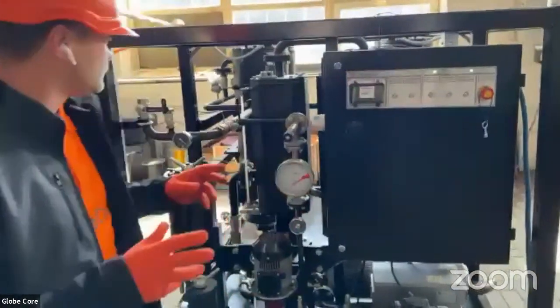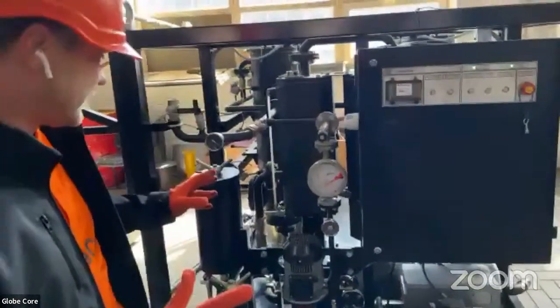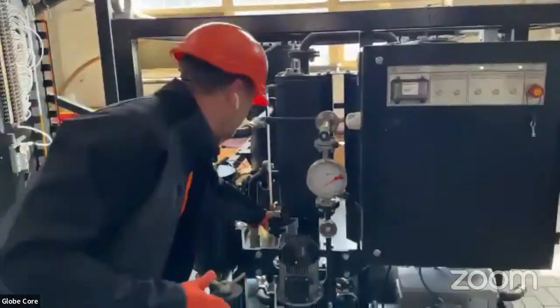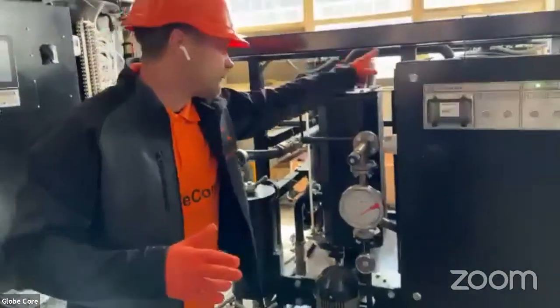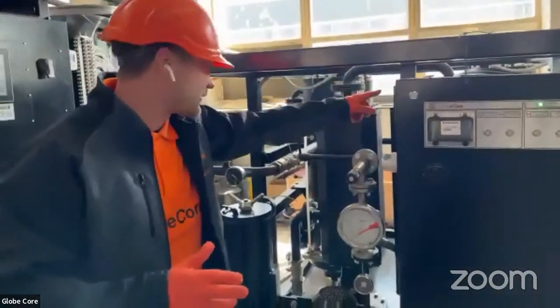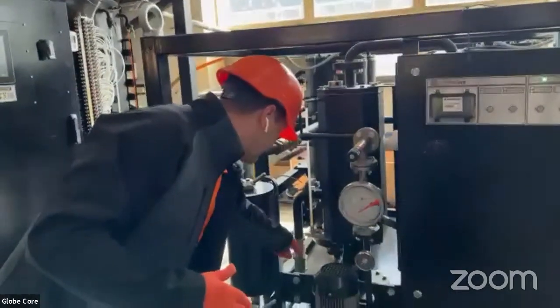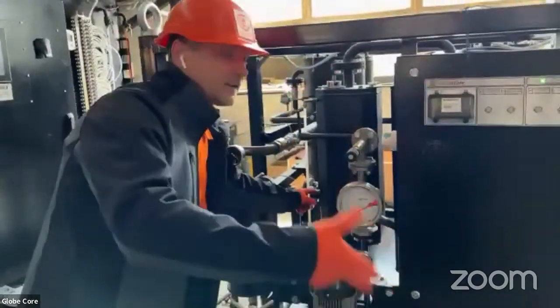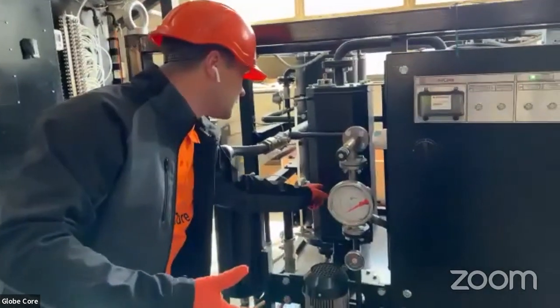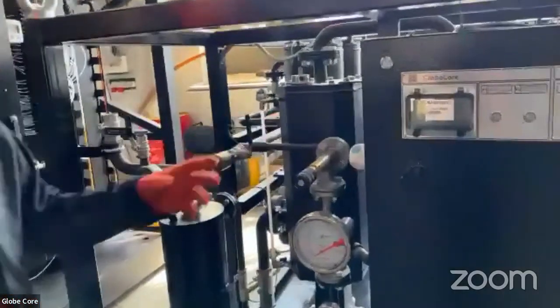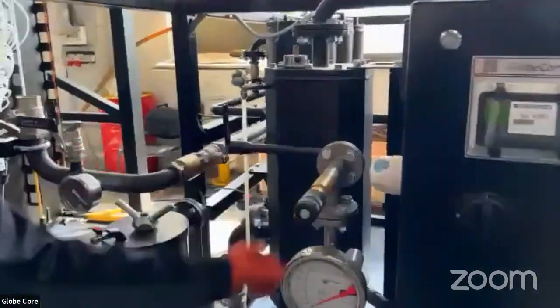Another additional vessels in here. The first one is the demister. It is on the way of the vacuum, of the air actually, from the intermediate tank. Air with the combustion products goes to the demister, where the liquid phase is condensed and can be removed.